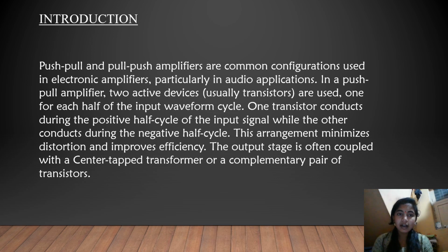Let us come to the introduction of this push-pull amplifier. Push-pull amplifiers are common configurations used in electronic amplifiers, and they are particularly used in audio applications. In a push-pull amplifier, there are two active devices, transistors, one for each half of the input waveform cycle.